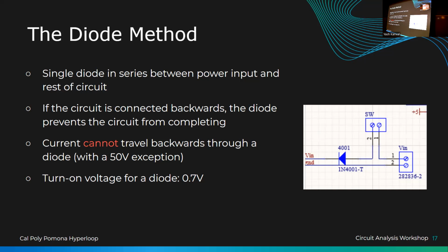Let's say you are doing a project that uses a 3.3 volt cell battery, about this big, and you put a LiPo there. Let's say your IC chips, or whatever you're trying to power, run on 3.3 volt logic. If you put a diode there to protect your circuit, you're losing 0.7 volts from 3.3 volts. You're getting 2.6 volts on your IC chips, and that's not enough. You're lowering the voltage on your circuit.